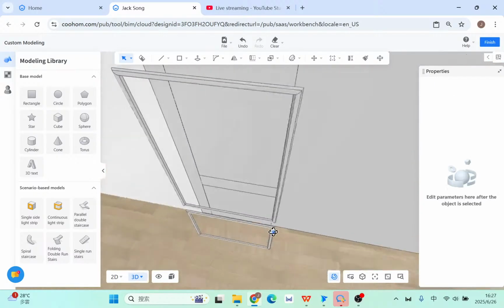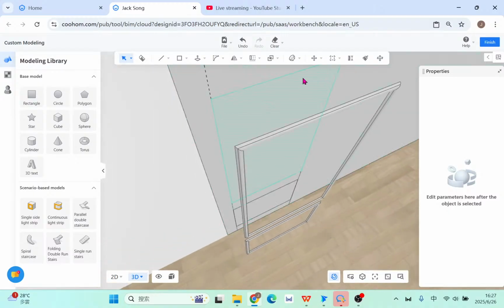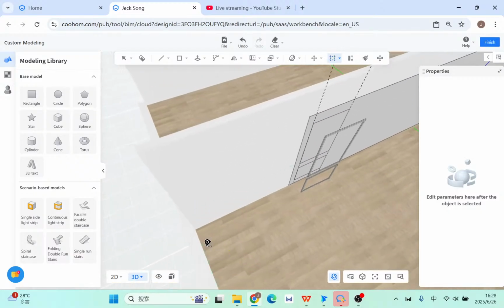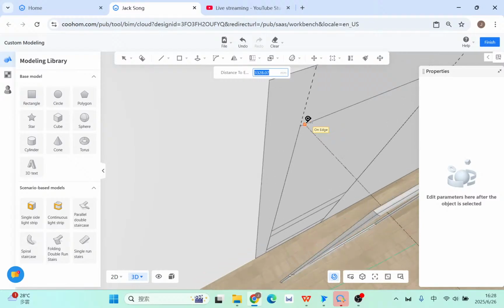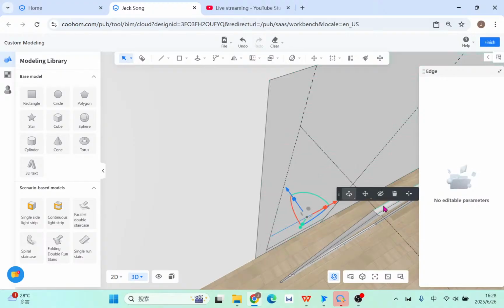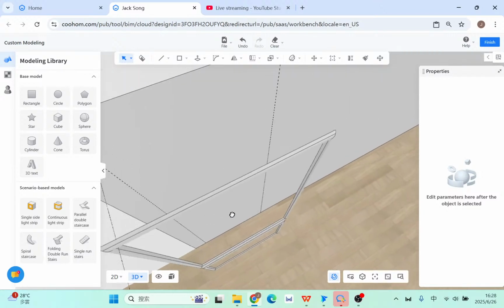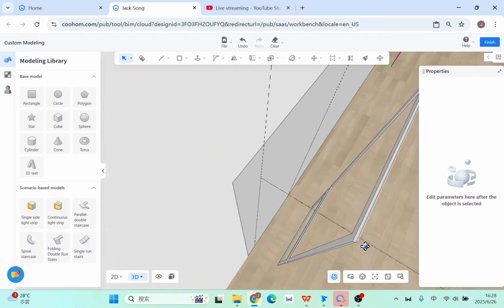Rectangle. Now we have this. And then don't forget to give a reference line to mark out the point, because later you might miss this one. You might miss the position. Just mark out the endpoint and also delete the line, because any extra lines will cause calculation errors later. What you need to do is just mark out this one, okay?